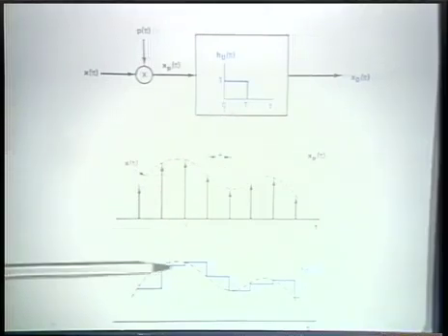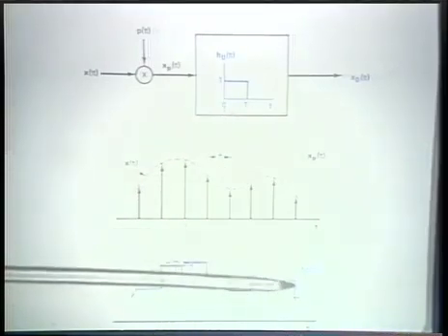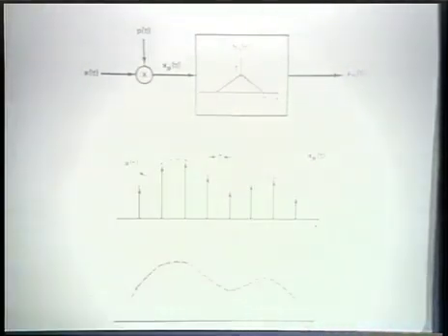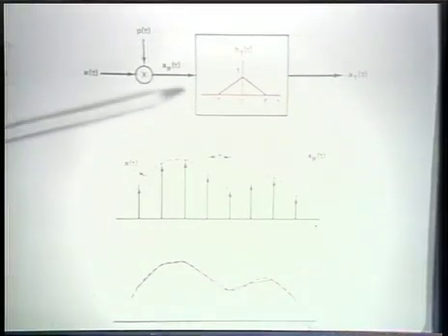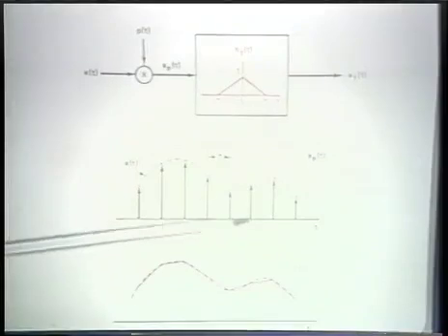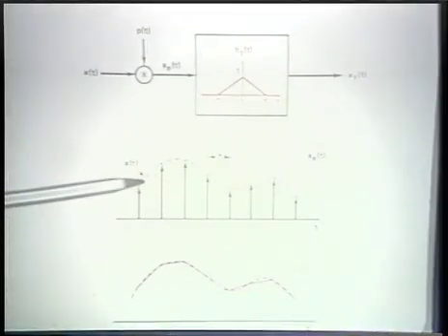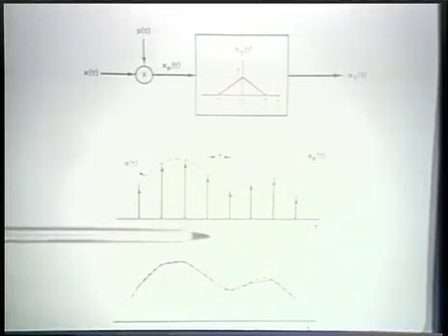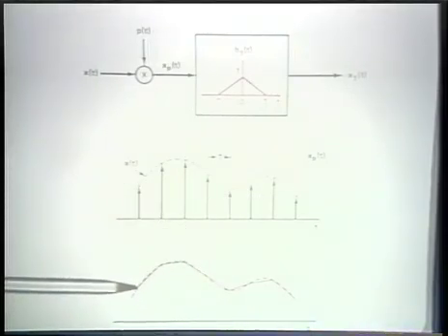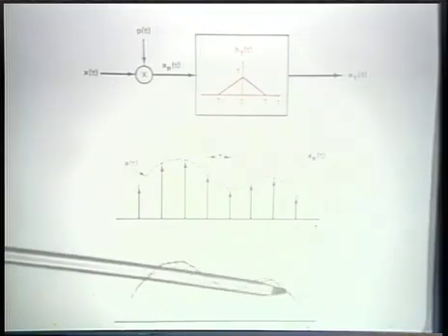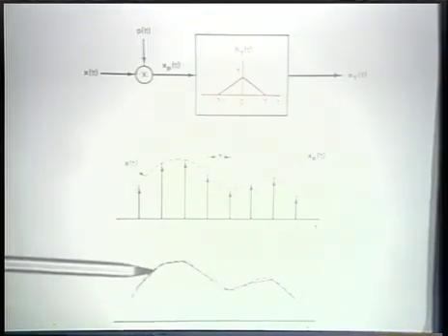That will generate then our approximation, which is a zero-order hold. And following that, we'll do exactly the same thing with the same waveform using a first-order hold or a triangular impulse response, in which case we'll see again that as the triangle moves along here and we build up the running sum, or the convolution, we'll fit the original curve with a linear curve.